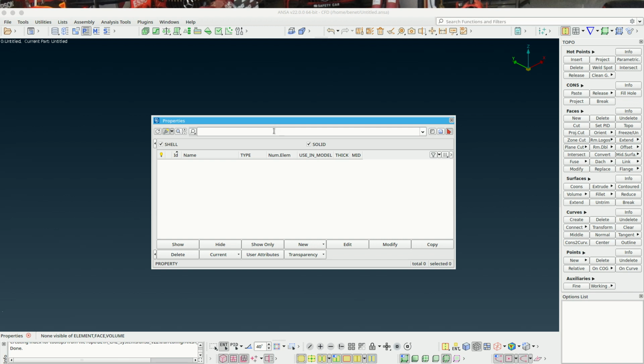But what's important about PIDs is that afterwards, to set different boundary conditions, we are going to need different PIDs. What's clear is that we're going to need a PID for the inlet, a PID for walls, a PID for symmetries, and a PID for the outlet. Those are going to be our minimum PIDs, but then we can also have more PIDs with the same boundary condition. And for example, we can use these different PIDs to play with their visibility.